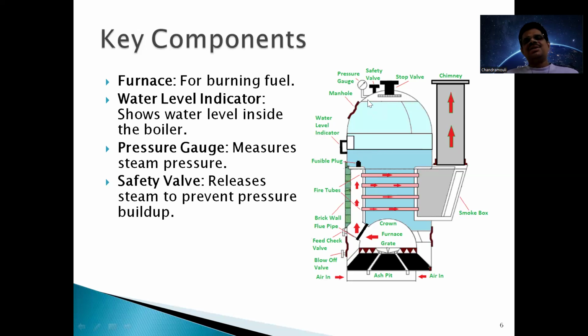So this is just similar to our pressure cooker whistle. Our pressure cooker is also a type of boiler. There also you heat the water and steam is produced while cooking. Okay, and at the top you observe a weight. This weight is nothing but a safety valve. So what happens when you cook food in a cooker? After some time, steam is formed, and the pressure of the steam gradually rises. As and when the pressure is raised, this pressure is enough to lift the safety valve.